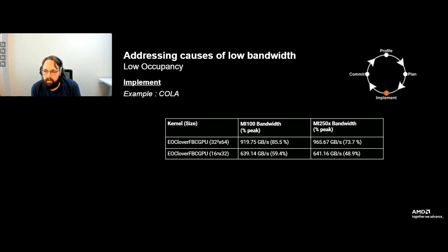Remember, the MI250X GPUs support fewer wavefronts in flight, so it's a little bit harder to do the latency hiding like we get on the MI100s. There are just a lot more wavefronts in flight on the CDNA architecture, so there's a little bit more trickery that we have to do on the 250X.